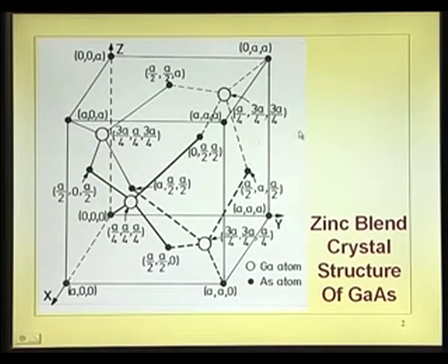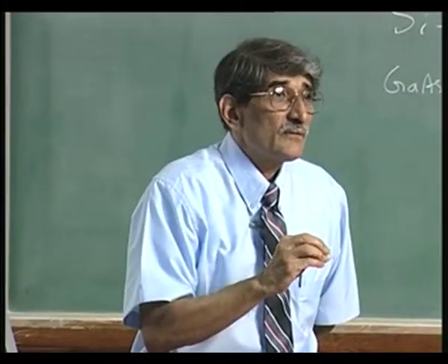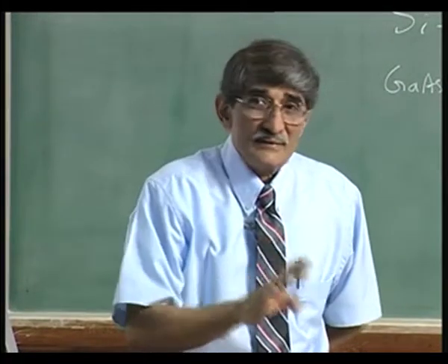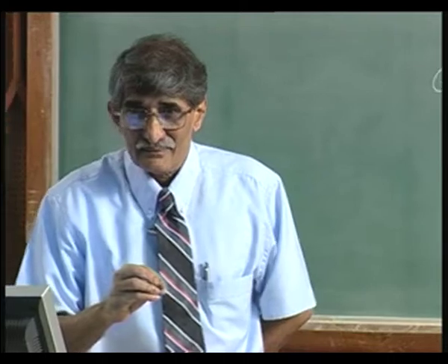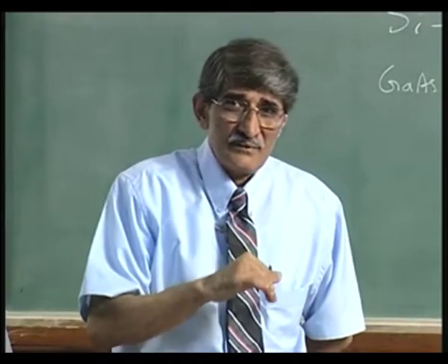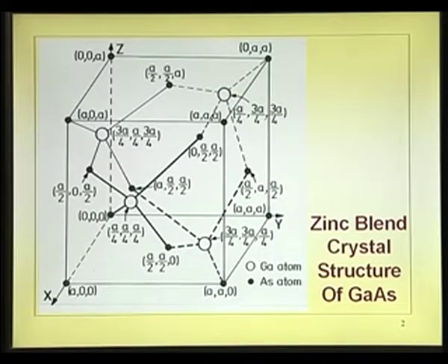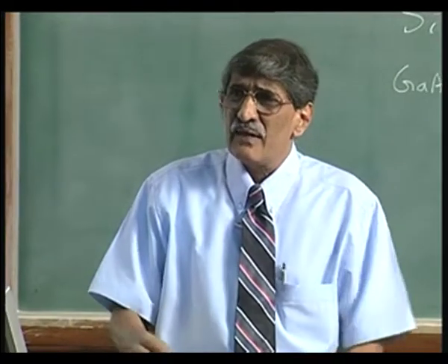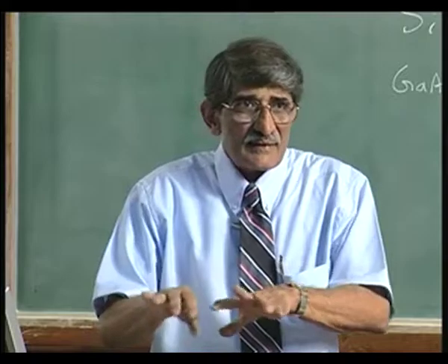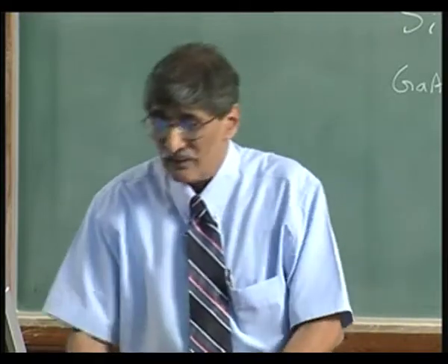Here you can see these are the lines which I have drawn, because gallium has got 5 valence electrons. This is the difference between silicon and gallium arsenide. Silicon has got 4 valence electrons. Okay. Now, on an average, therefore, for gallium and arsenic there are 8, like in silicon. So, this structure also forms covalent bonds. This also forms covalent bonds like silicon, but in addition to that there may be slight ionicity because of slight negative charge, that we will discuss later. Right now we will see.